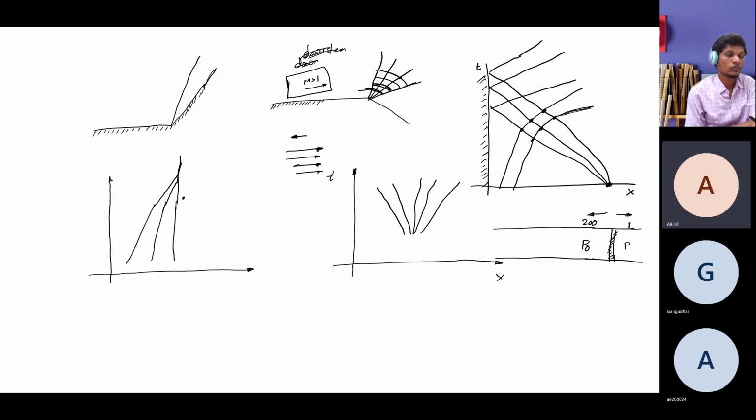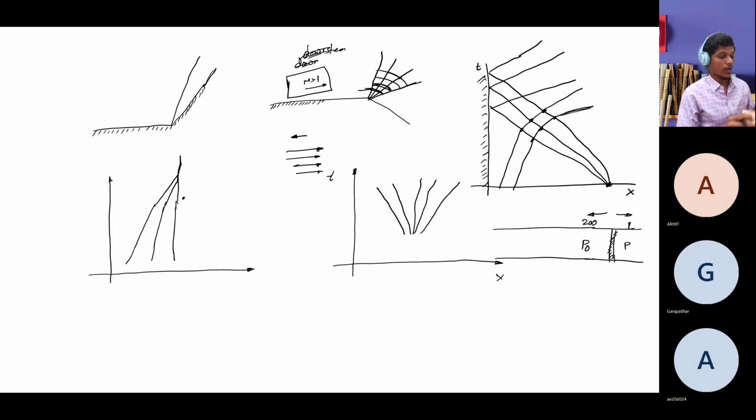Sir, in the last assignment question, it was written bound vortex only. Yes, I clarified that question, I forgot to mention it to you. That question is actually asking why the bound vortex concept, or the Prandtl lifting line, what he is trying to do in the finite wing theory. Suppose it is your finite wing, even if it is an infinite wing airfoil, what is the primary thing that we need to model around the wing?